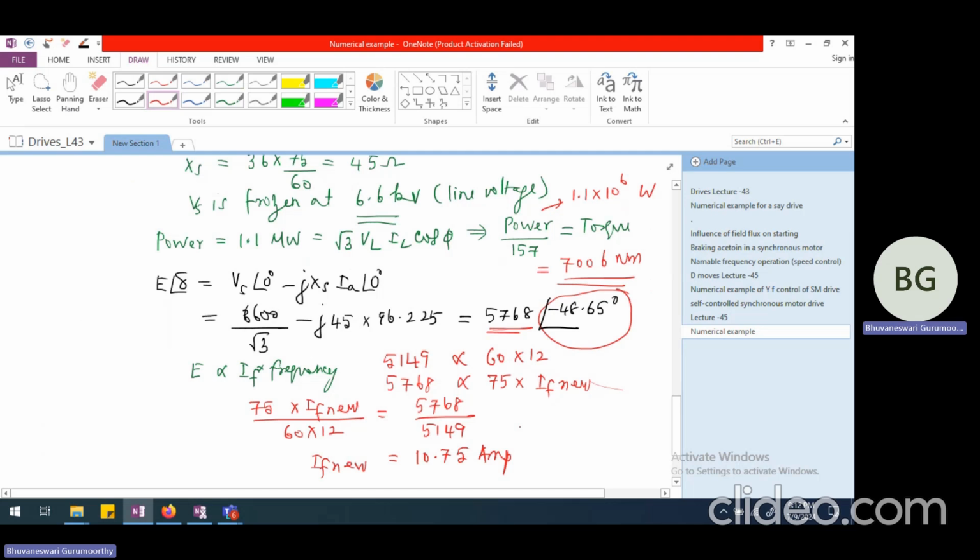So when we are looking at a lower value of torque being supplied by the machine, and we are at unity power factor, the excitation can be decreased because the flux is also decreased. So this is going to be definitely lower, right? This explains how the synchronous motor functions in variable frequency, variable voltage mode of operation using a voltage source inverter.